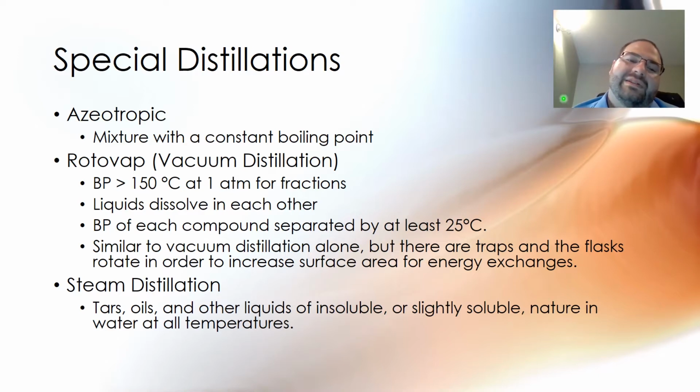And so what you have to do when you have an azeotrope is find a compound that azeotropes with the compound you want separated from it better. And in most cases they use benzene for water, because water and benzene have this other azeotropic effect where the water wants to stay with the benzene. And it does. And you use this property for other kinds of things.